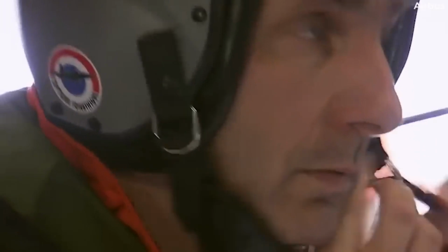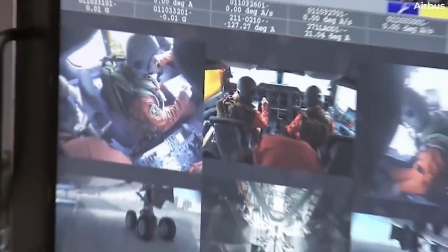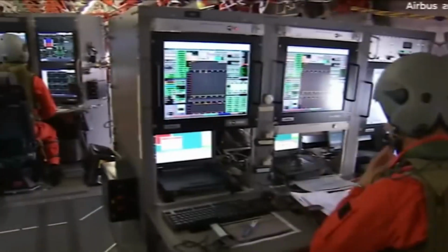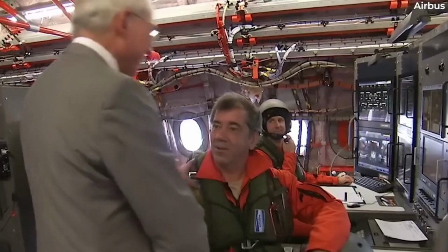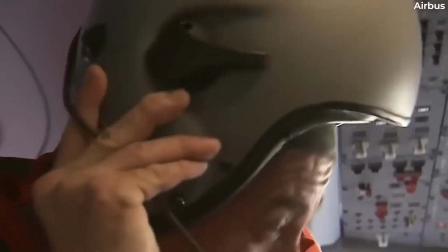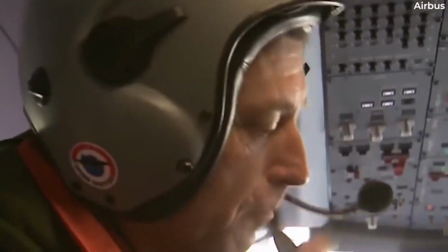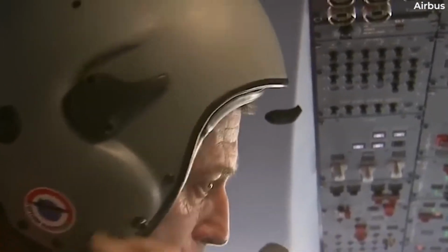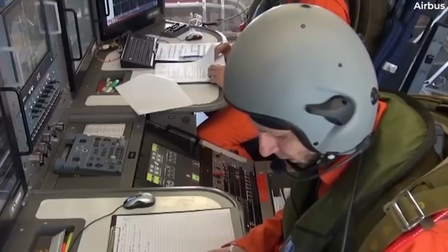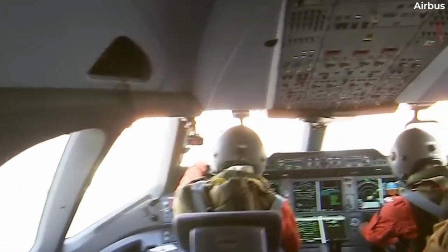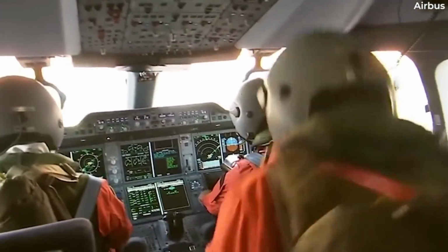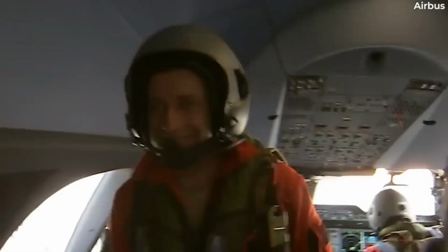It may also help the reader understand when 14 CFR Parts 121, 125, and 135 regulations apply, by taking a brief look at a list of flight operations where 14 CFR Part 119 does not apply. 1. Student instruction. 2. Nonstop sightseeing flights with less than 30 seats and less than 25 nautical miles (nm) from the departure airport. 3. Ferry or training flights. 4.